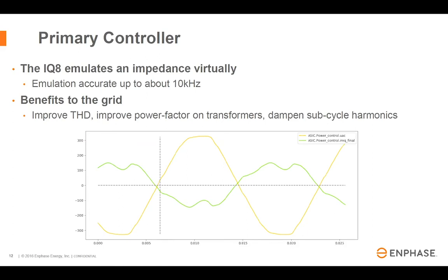This shows a little diagram of me very temporarily, if anyone's from PG&E, pretend this was just a simulation, running grid forming controls on my house. Like I said, I'm at the end of a long lateral, so I actually have quite a bit of third harmonic in my grid. I was surprised by how much third harmonic the grid had. I was barely in compliance with the ANSI limitations.